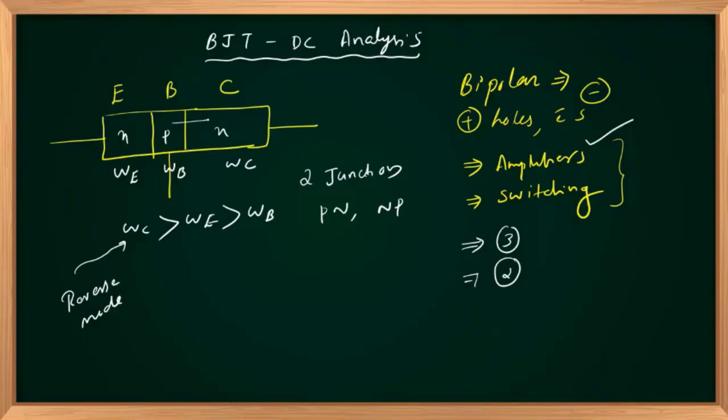Due to the collector current flowing through the reverse biased junction, there will be a heat dissipation in the collector region because the carriers are accelerated and flowing through this collector region that is reverse biased. So there exist atomic collisions that will increase atomic vibrations, that in turn increases the heat in the region. So to dissipate maximum heat, we are ensuring width or area of collector region is much larger than the other regions, emitter and base.